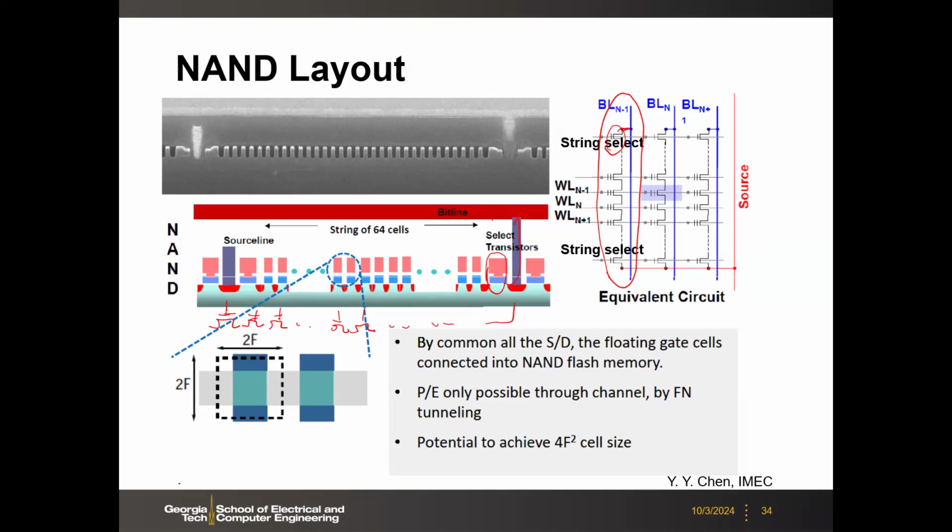Okay. So I would say that those are the floating gate transistors. We should have double line here. But at the end is a regular transistor. Okay, so if you look at one cell along the string, here you have this kind of layout. So the key is that the floating gate transistors between those two, they're in series. So you do not have the source, even though this is source and drain of the transistor, right? And you have the gate.